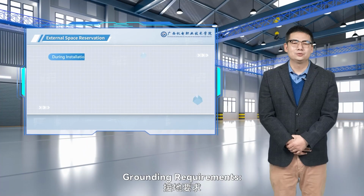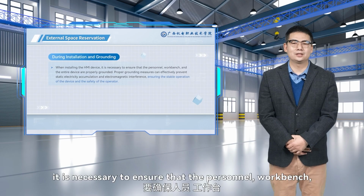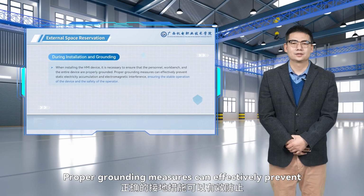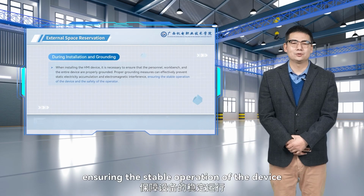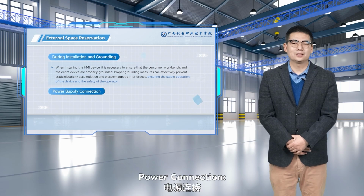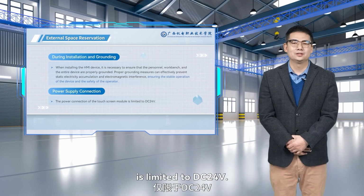arrangement. Grounding requirements. When installing the HMI device, it is necessary to ensure that the personnel, workbench, and the entire device are properly grounded. Proper grounding measures can effectively prevent static electricity accumulation and electromagnetic interference, ensuring the stable operation of the device and the safety of the operator. Power connection. The power connection of the touchscreen module is limited to DC 24 volts.